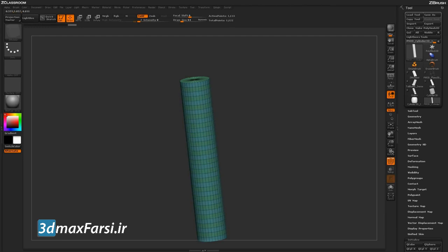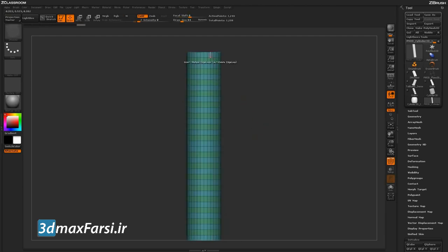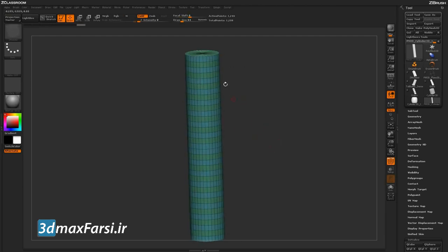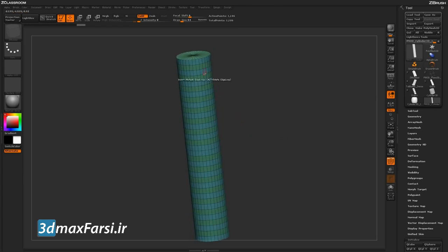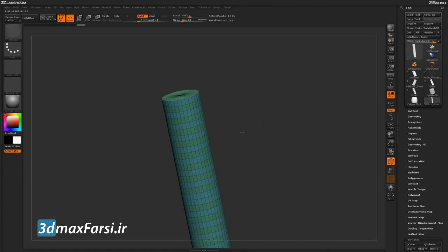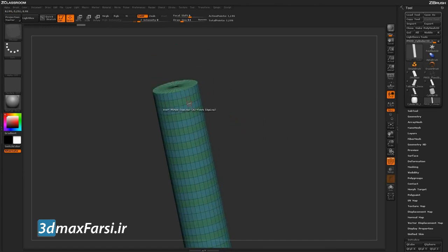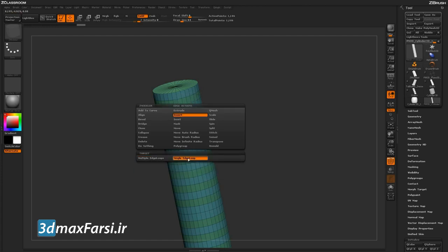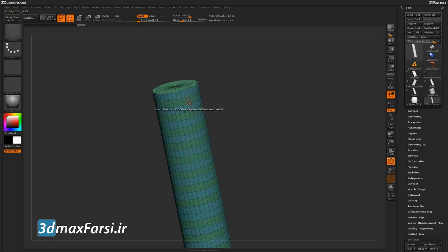Now I don't need this much edge looping established, but I basically wanted to make sure that any single area where I have this joint section being created, it's a consistent size. So I'm actually going to come through now and remove some of these excess poly loops that I no longer need. To do this, I'm going to hover over an edge again, press spacebar, and now select a single edge loop. And now if I hover over an edge and, while holding Alt, click, I can start removing some of these edge loops on my model.